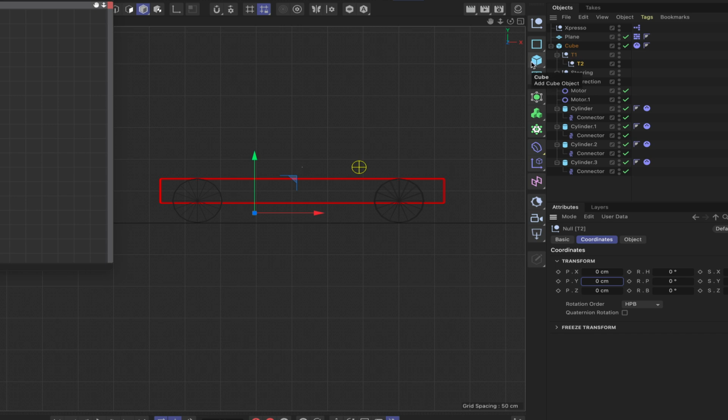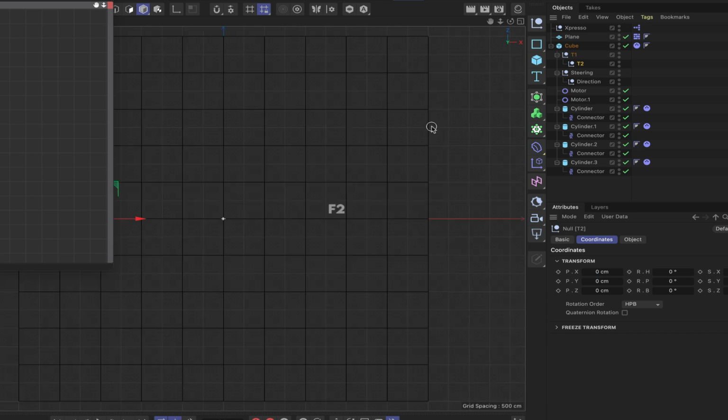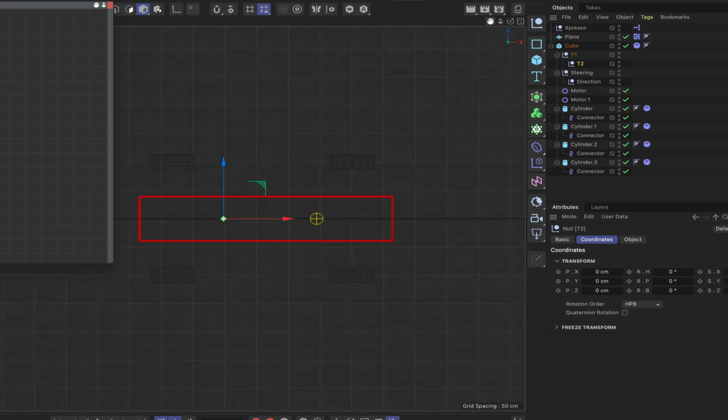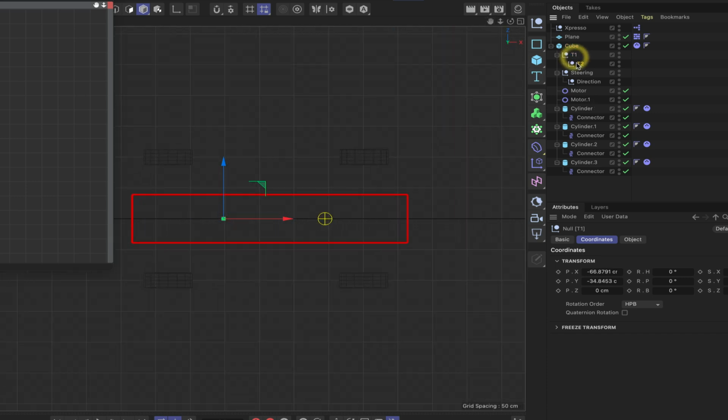But they need to be set differently to how they are at the moment because they're not quite there. Their Z positions are not right. So let's just switch to our top view and object and zoom in so that we can see where we are. Right, so let's just separate them and we can put T1 over here and T2 over here. We can actually say minus 100 for that and 100 for that just to make it correct.